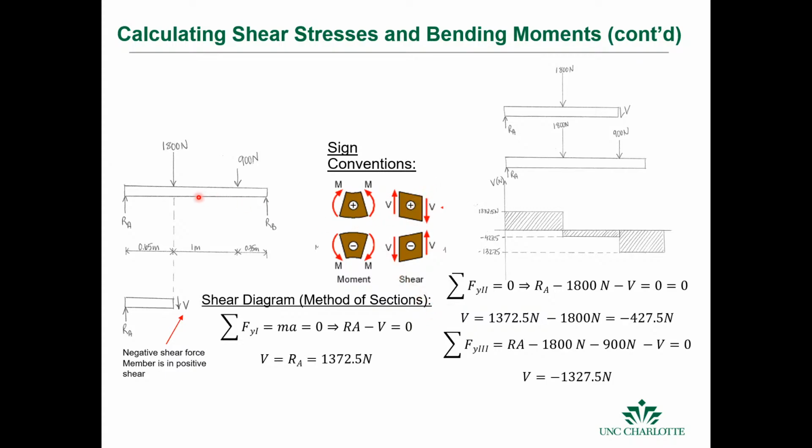Okay, and the way we draw the shear diagram is we essentially start at a side, and we go over and we slice it. And then we say, well, what does the force have to be on this surface in order to counteract this load condition? Then we just have this V, which we call our shear, and as we move along the surface, we can cut it each time, and we can see what V actually is.